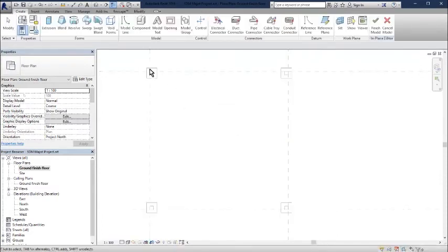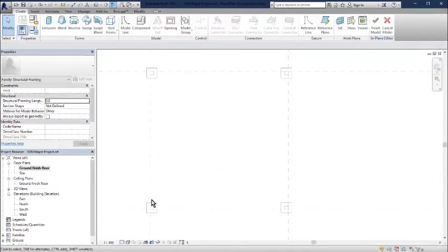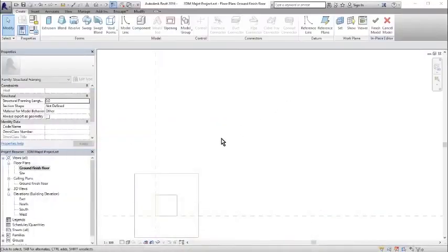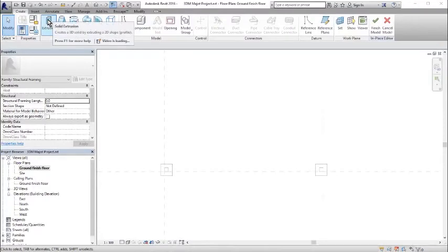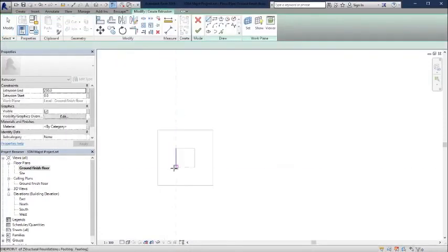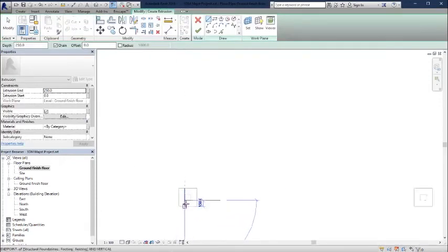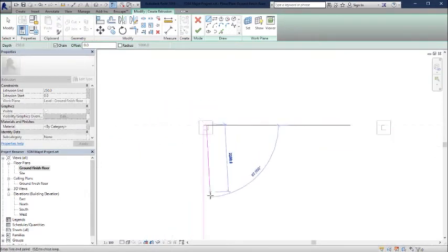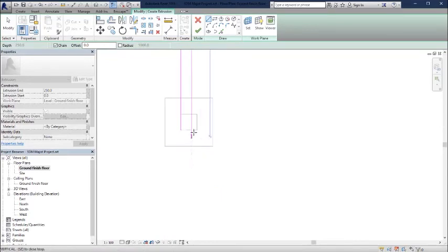And this member, remember, is going to be 100 by 100, and we're going to let it run on the outer section of the foundation, right? Which is what is happening here. So to do that, we are going to make it an extrusion, and we're going to actually have one member starting from here, up and over by 100, and down again. Of course, you could also use the rectangle sketch to do that. Great.